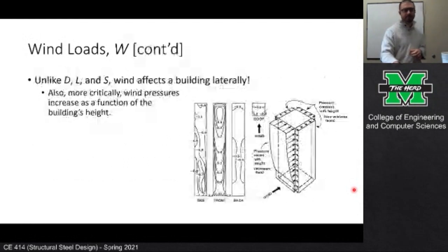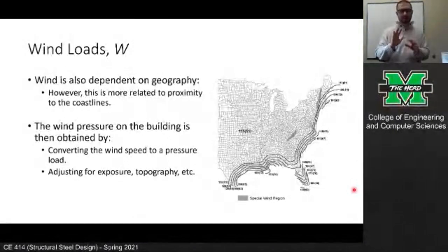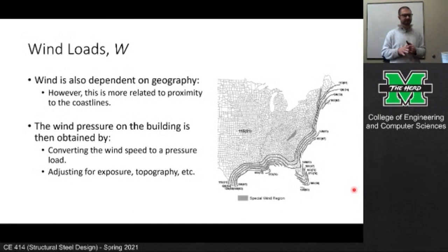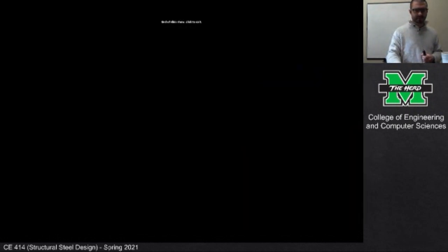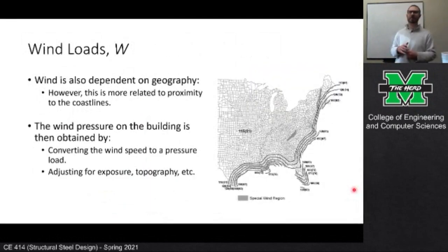One of the other things that pops up with environmental loads is what's called a risk category. So there are 4 risk categories. Let me see if I put those in here. No, I didn't. I'll just give you the brief overview. So there are 4 risk categories assigned in ASCE 7. Risk category 1 are unmanned structures like grain silos or abandoned or empty warehouses and stuff like that.